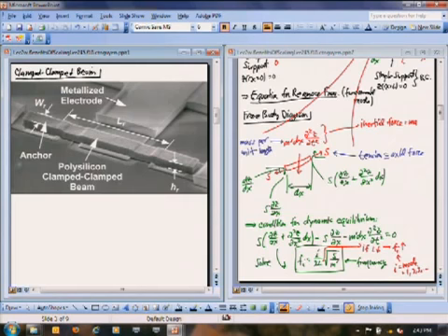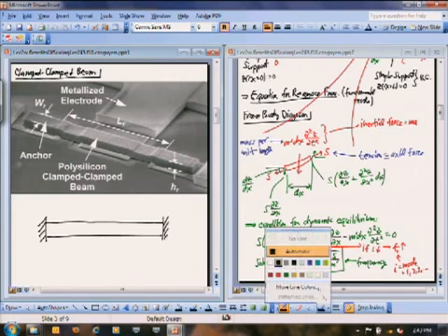That's going to have a certain finite thickness, of course. And the boundary condition, instead of those little triangles, I'm going to make that the boundary condition. This is a different boundary condition because what it's doing is it's actually enforcing that that angle remains 90 degrees at both those ends. So when this beam actually contorts to vibrate, what it's really doing is keeping its 90 degrees at those ends and just contorting like this.